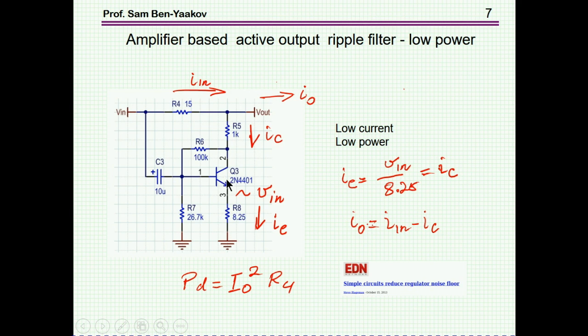Here we have a transistor again, but it is in a shunt configuration. This is the noisy side, this is the load side. Now we look at the ripple here, and actually it's fed to the base of the transistor at high frequency. The impedance is very low, so the voltage here is about the voltage here. I'm talking about the ripple voltage.